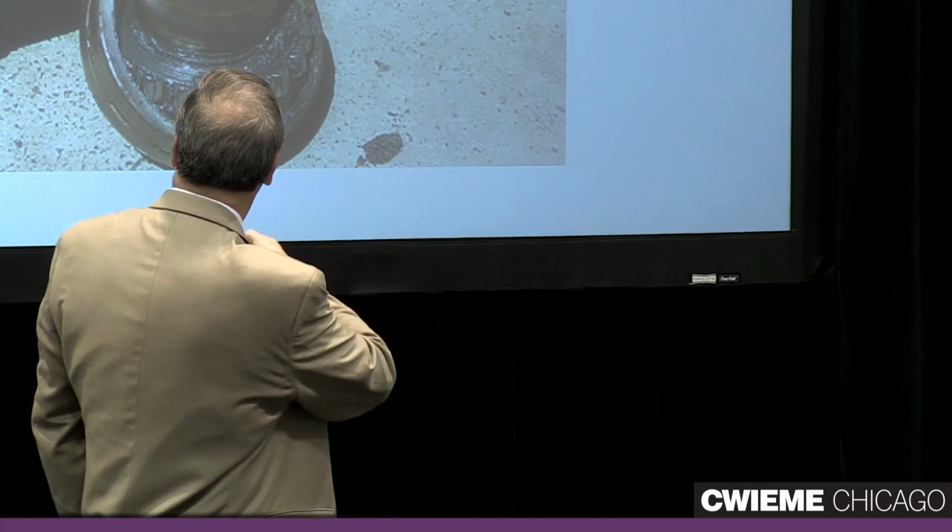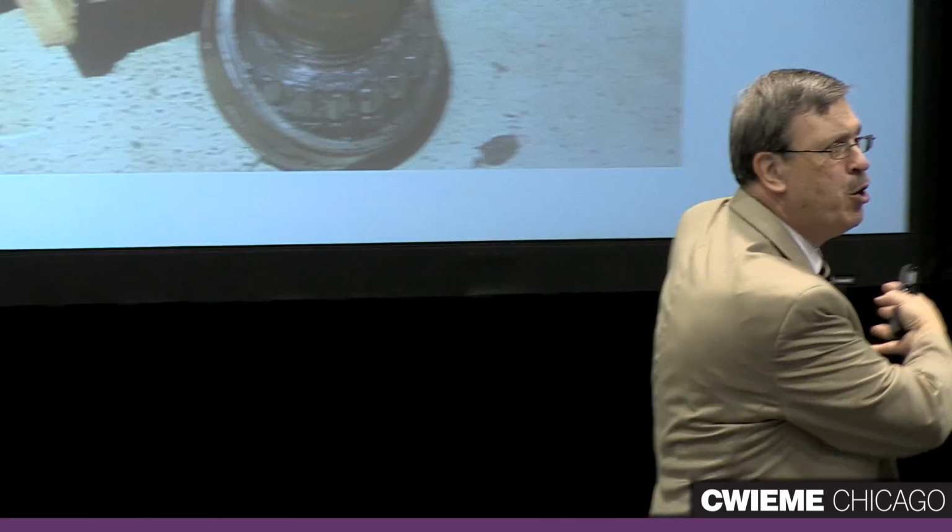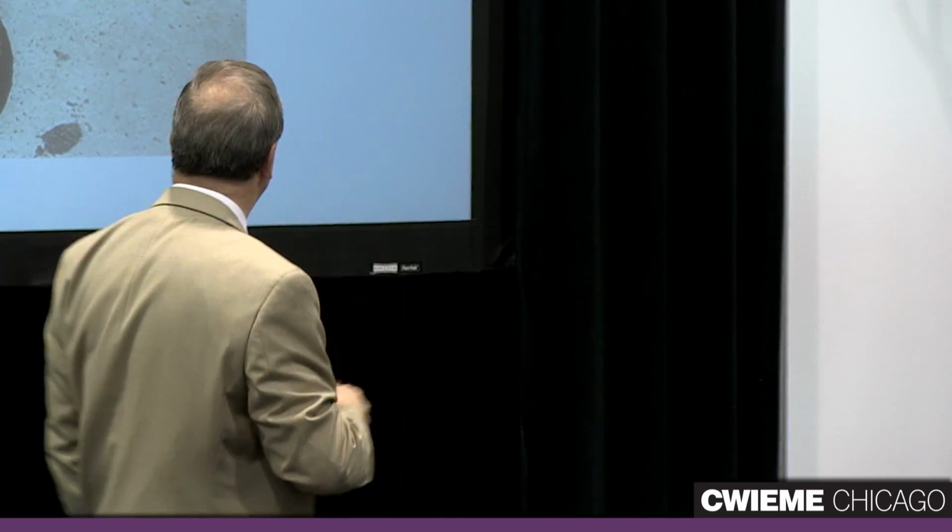And then also we have adjustable torque limit. And so you can control the amount of torque that motor is producing. When I talk about the mechanical jerk, that's not the derogatory term for the guy who was running this machine when that shaft broke, but it's a quick change in acceleration is what jerk is. And so things like this will not happen again if you have a drive on that motor.